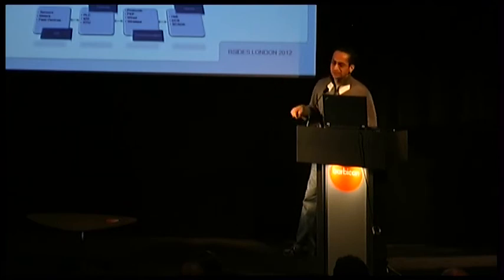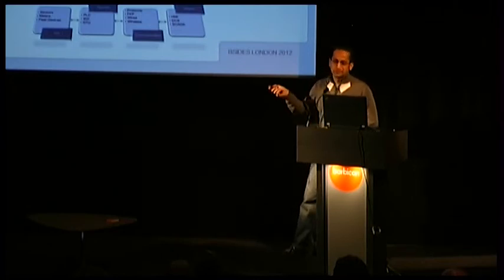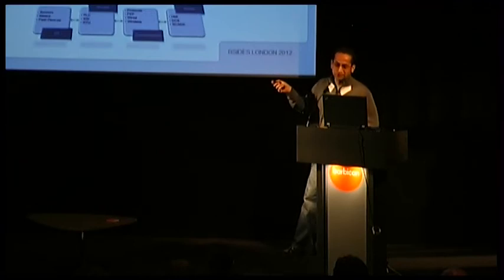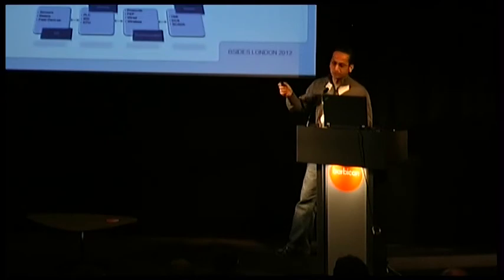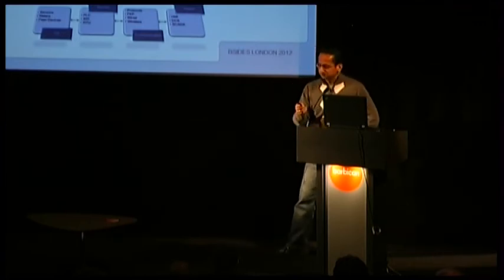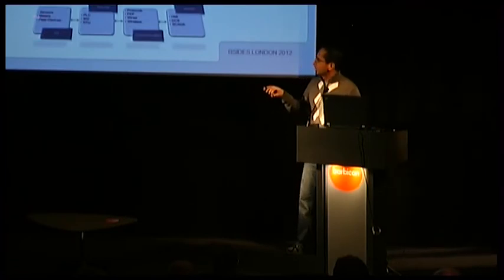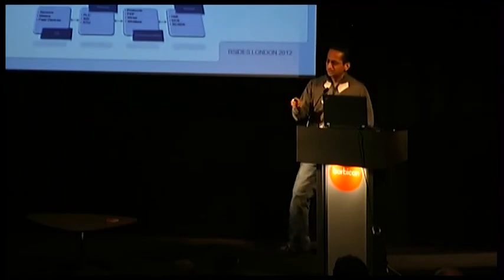And what these components do is they convert the analog or discrete measures to digital. So the examples here, on the extreme left, there is a PLC, there is an IED, and here there is an RTU. And to just give you a sense of how big these things are, I have included a picture of a man holding a PLC, which is mounted most probably on an electrical, I don't know, some sort of a pole here. I don't know what that is, but what he has is a PLC. So data is acquired by this component. There is a two-way communication to the data conversion component, which converts these discrete measures to digital.